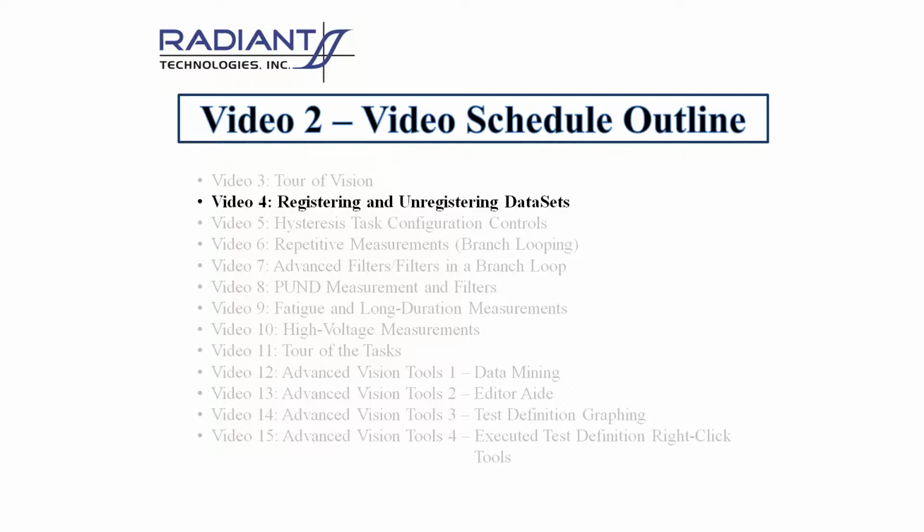On the other hand, the Dataset Explorer may become very cluttered with datasets. Unused datasets can be easily unregistered from Vision to clean up the Dataset Explorer. The actual dataset file, start.dst, can be left in place or even moved on the hard disk and re-registered with Vision at any time it is needed. This video will also briefly touch on searching for datasets and sorting them in the Dataset Explorer.